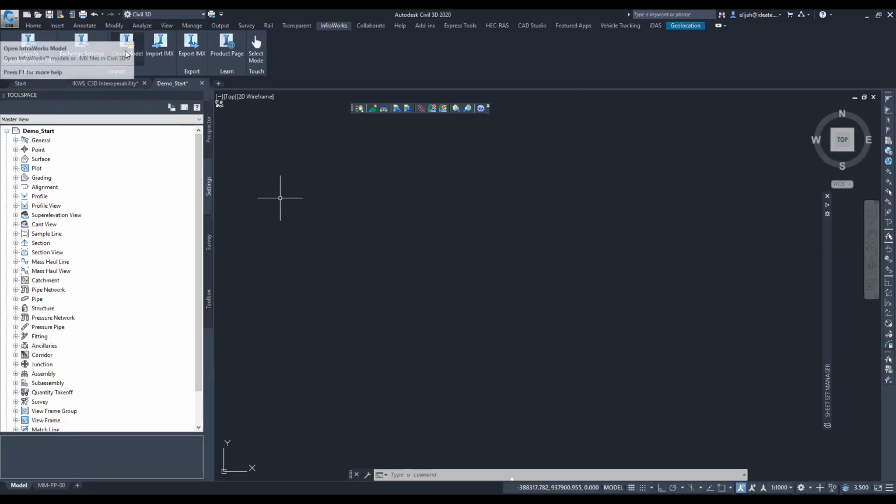Alternatively, you can open that entire model as I had said, but that usually consumes your time and it may bring in even some component of the model which you do not need to use within Civil 3D. So I said IMX allows you to only use the specific portion of the model that you are interested in. So again, you click on import IMX file. It takes a few seconds and it will bring up the model within Civil 3D.